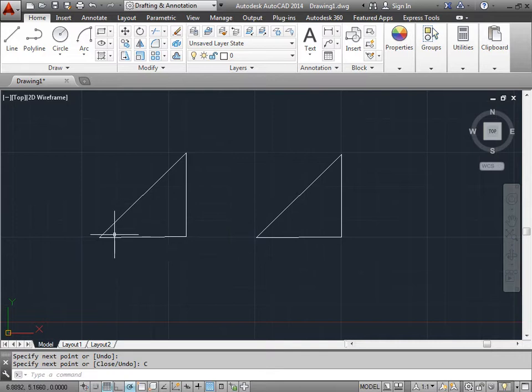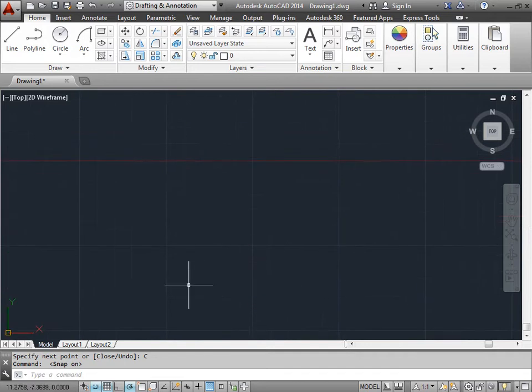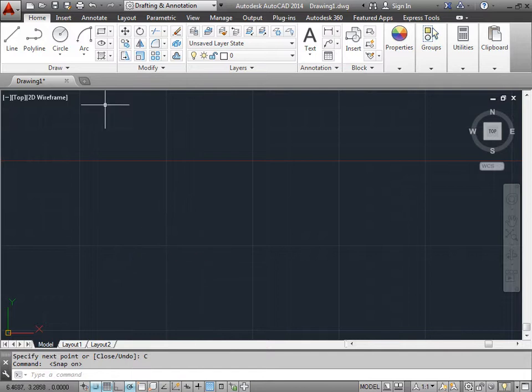But again, we have this crooked line here. It's just not matching up correctly or the way that we want it at all. Well, how about we turn on snap mode. We'll pan down just a little bit with the middle mouse button. And since we want a 45 degree triangle, I'll go ahead and put 45 degrees. And I'll activate the line command again.